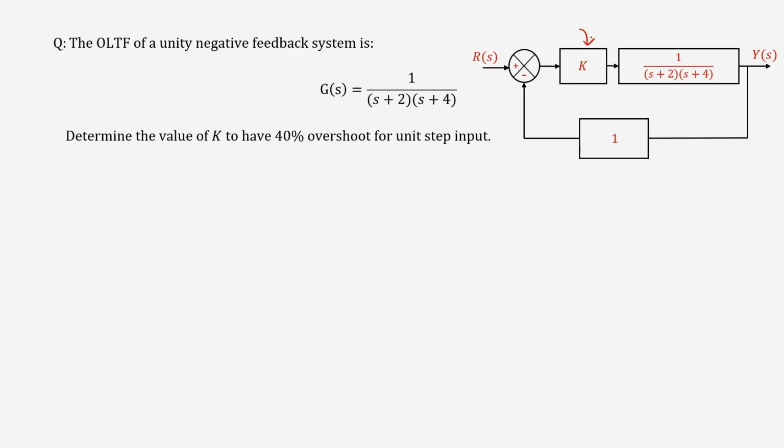Now, we are learning about these controllers where we are just using constant gain blocks. Later on we will replace those with other transfer functions, but for now we are just learning this. In most cases the base idea is that first you have to come up with the desired pole location. So, let us come up with the desired pole location first.